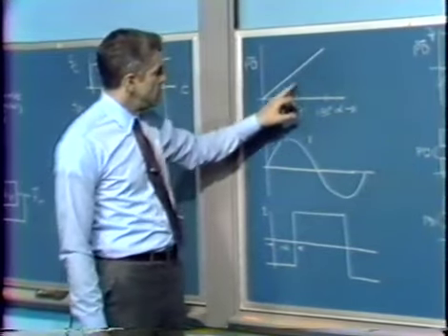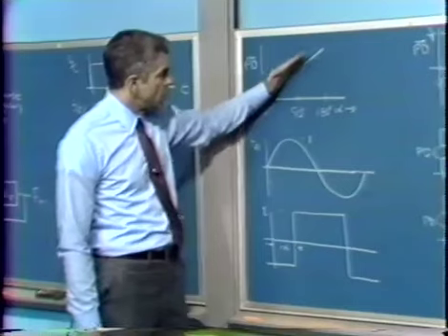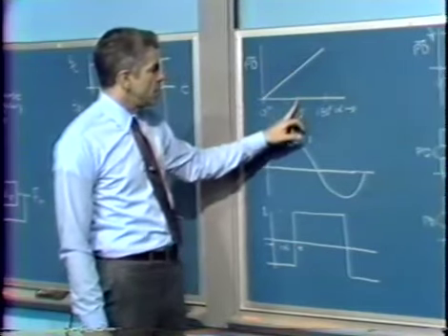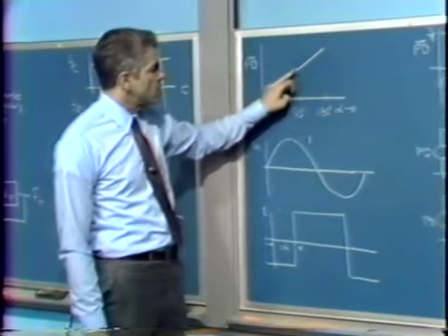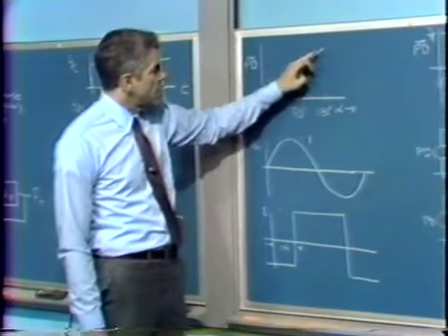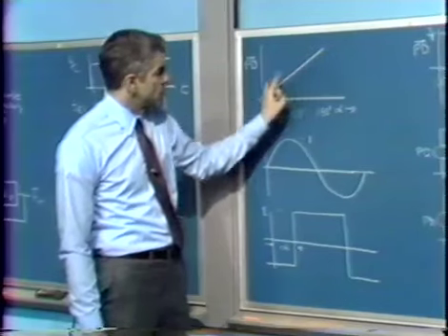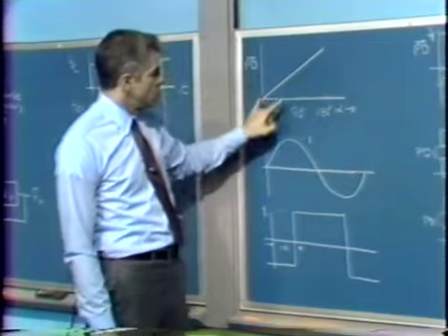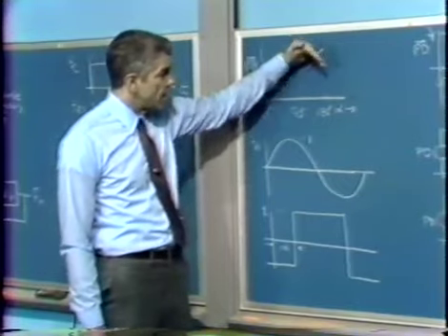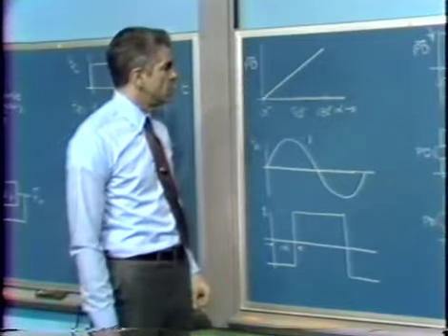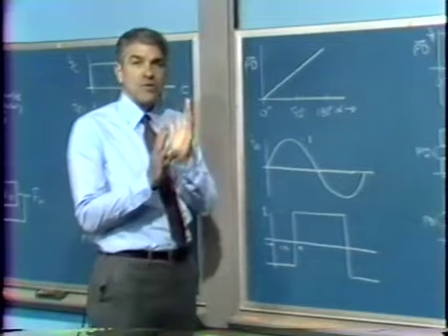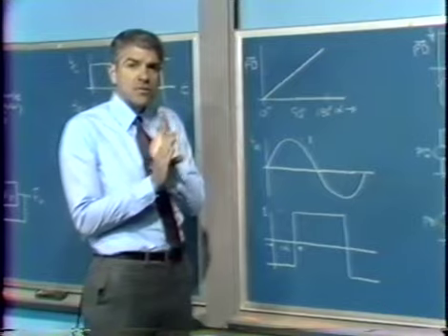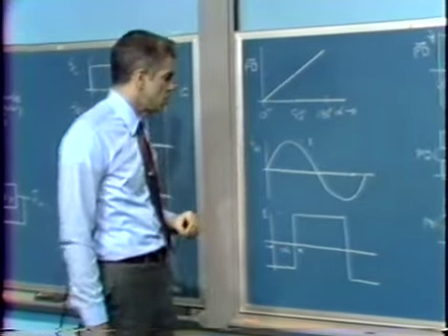Let's assume that this slope gives us negative feedback in our overall loop. We then presumably try to arrange the loop so that its operating point was somewhere in here. That would allow us a maximum of plus or minus 90 degrees of phase deviation between the two signals before we had a phase reversal, a polarity reversal in the loop. So we'd have a total range over which the loop would hopefully work normally of plus or minus 90 degrees of relative phase between the two signals.